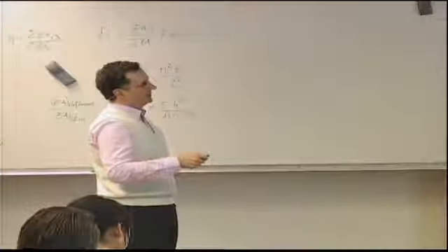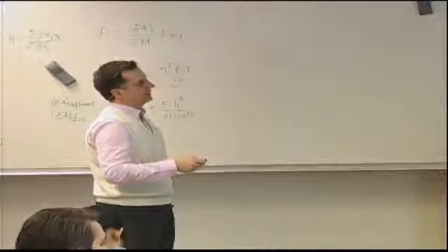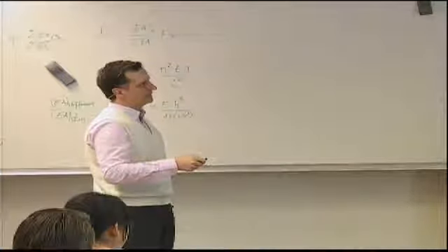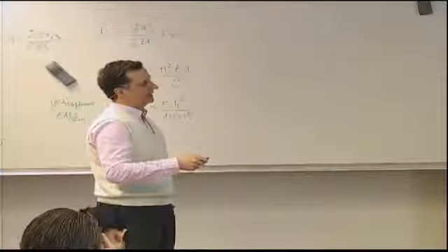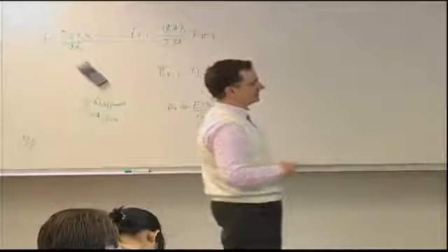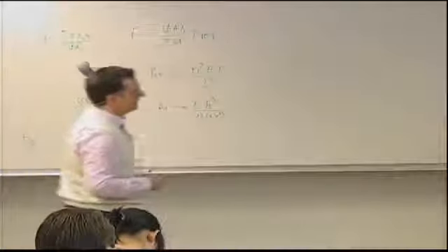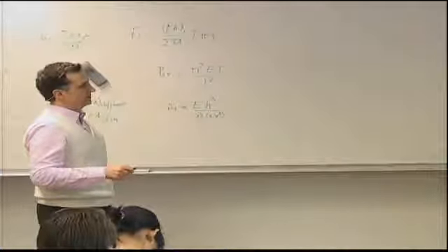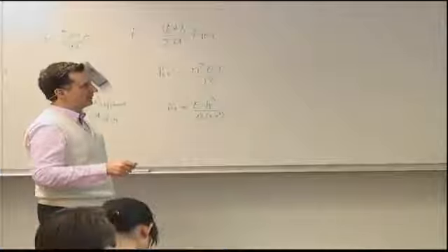So this is a good design for a flange, and this is a bad design because it has only this half fabric ply 0 and a 90, which doesn't do anything for a flange under compression, and then it has only these two 45s there. Looking at the ultimate strength for the two stacking sequences, you can see the significant improvement when you have more zeros.